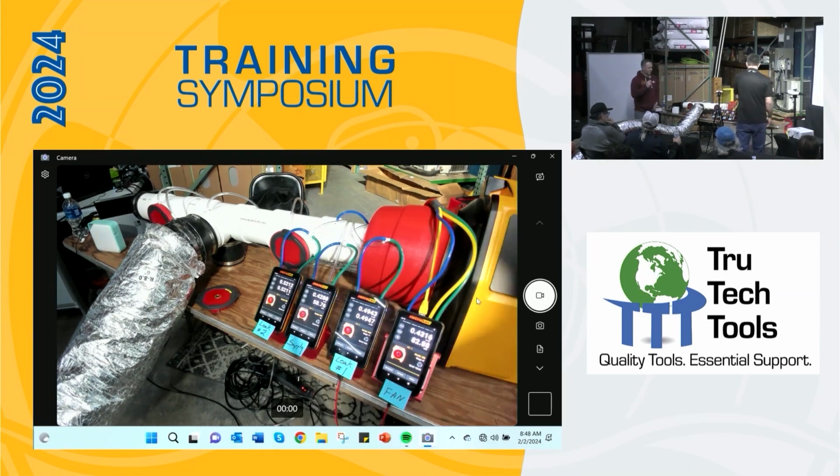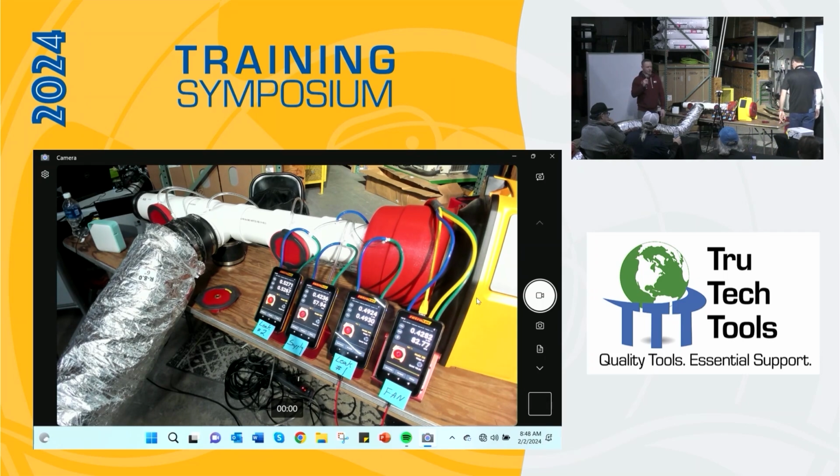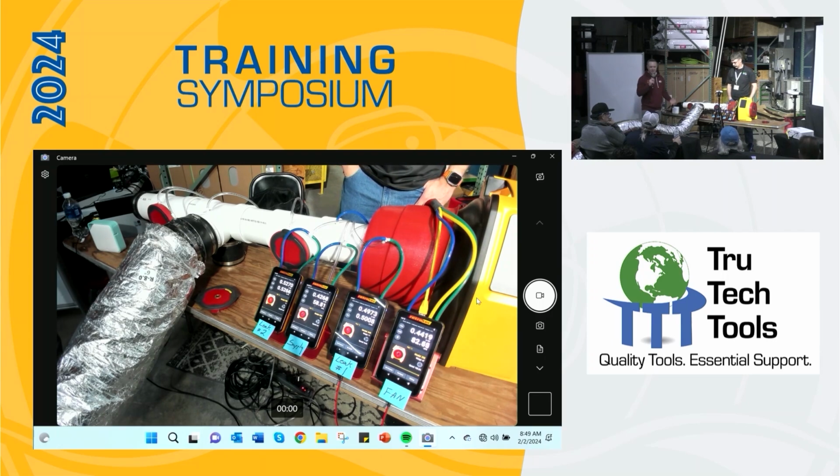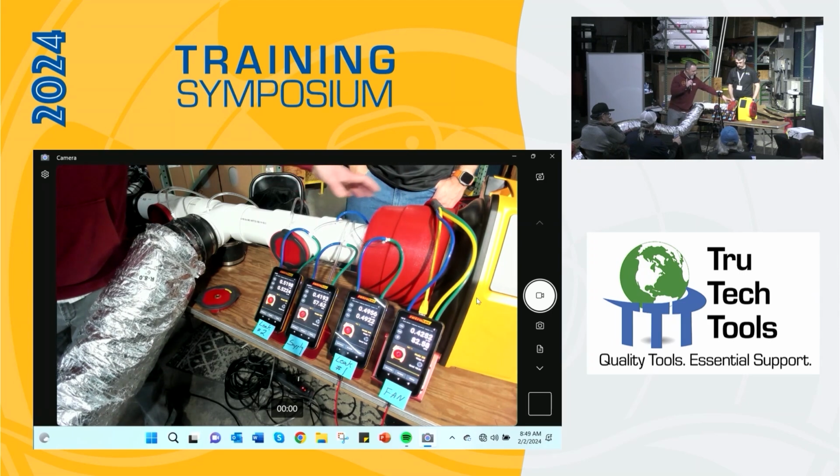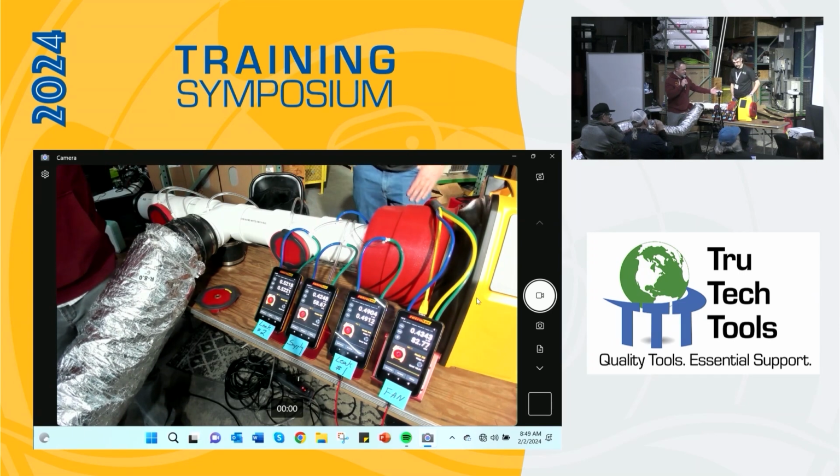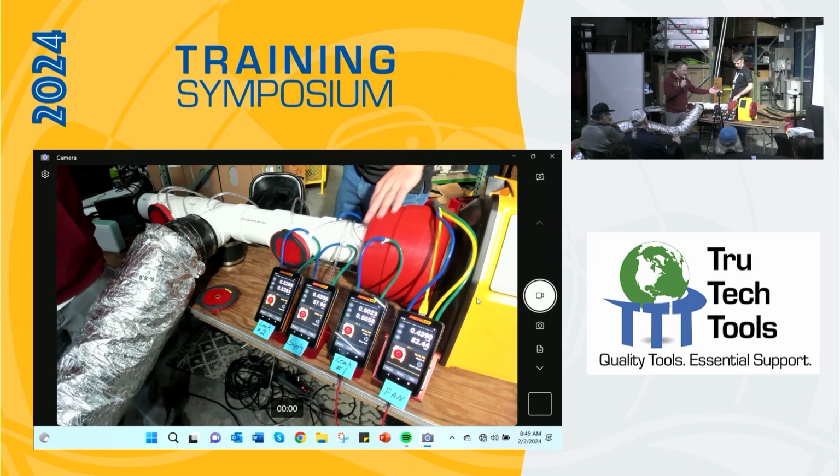If any of you ever wanted to do something like this, whether at your shop or at a training center, this thing was pretty easy to build. It's 4-inch PVC. There were a couple of specialty parts that you could still just make yourself, like this bell housing. This is just an attachment for the duct tester for the European system that we have, because they have smaller ducts over there.